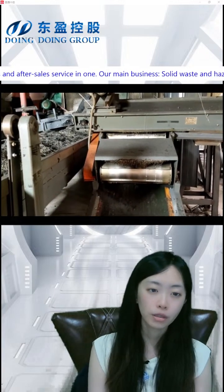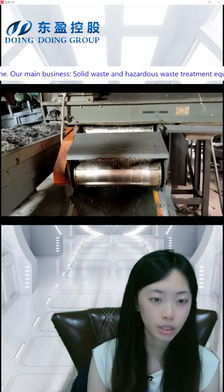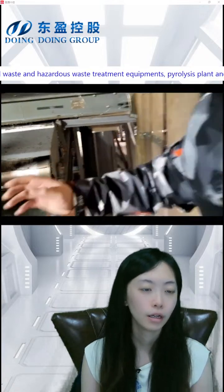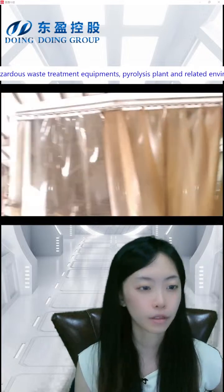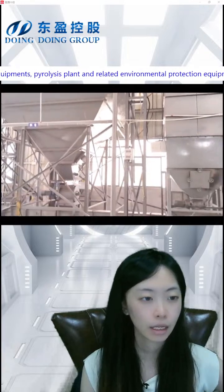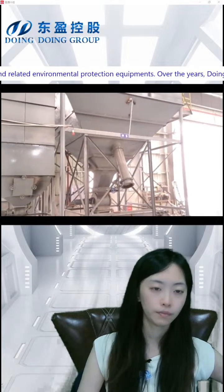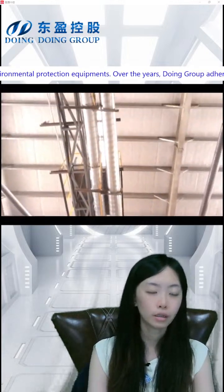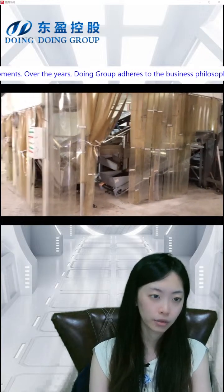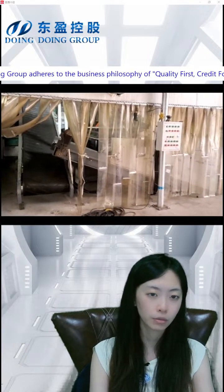And we can have the oil sludge also go through pre-processing to remove the water content, just as I said, by the centrifuge or the filter process. Or we can have the drying process by heating it. Most of our customers will use the drying process to remove the water content from the plastic. So you have the plastic, you can dry it before you pyrolyze it.